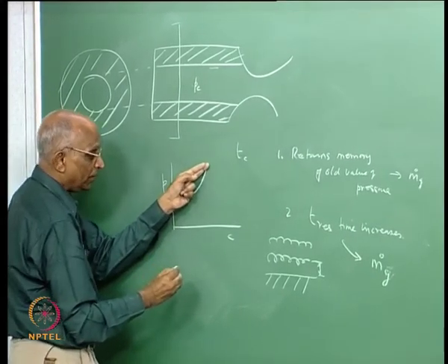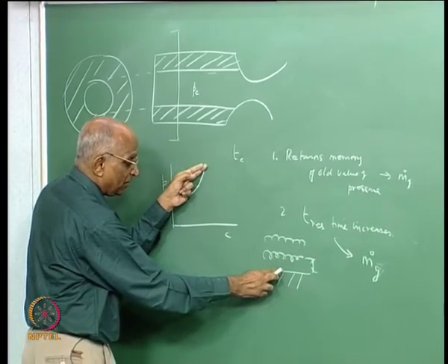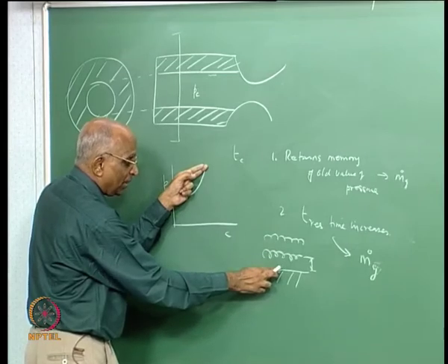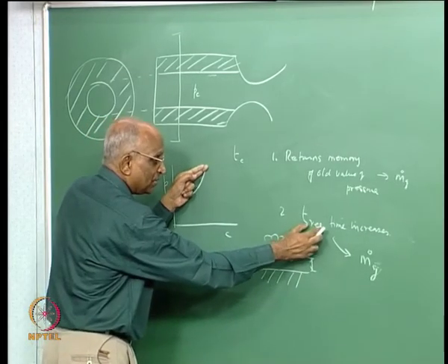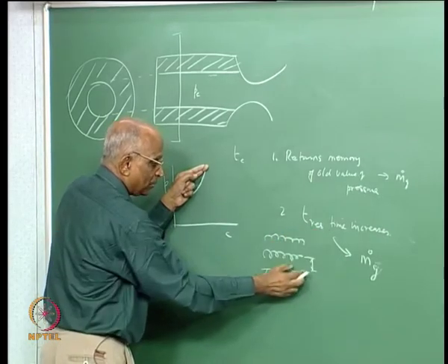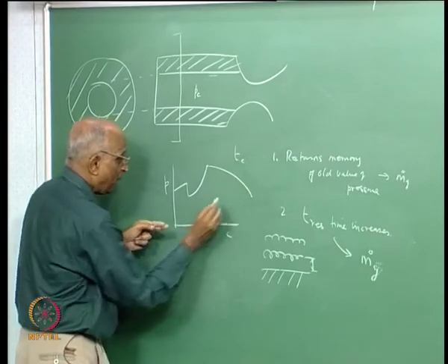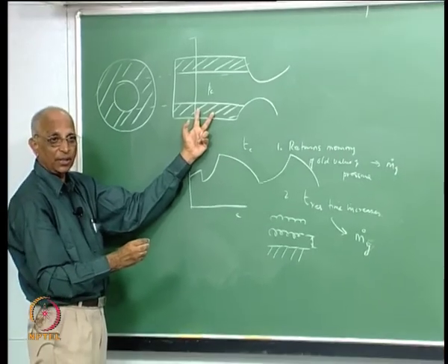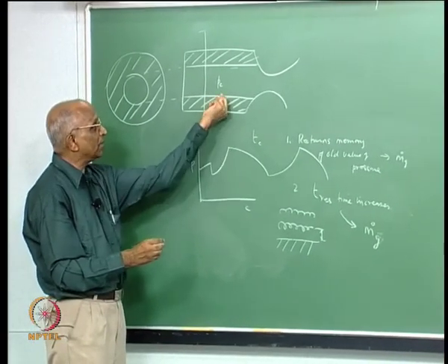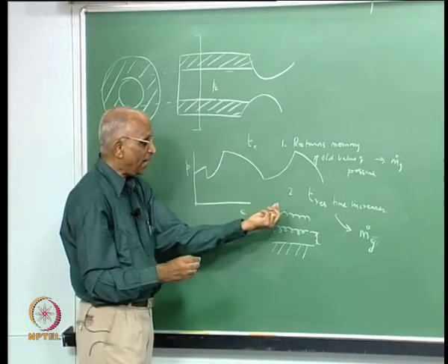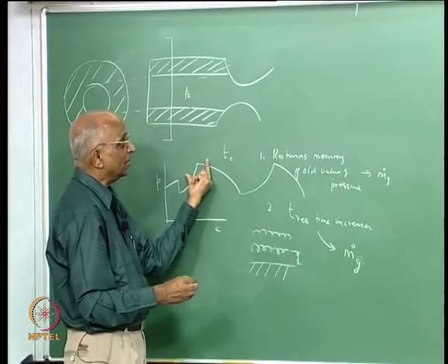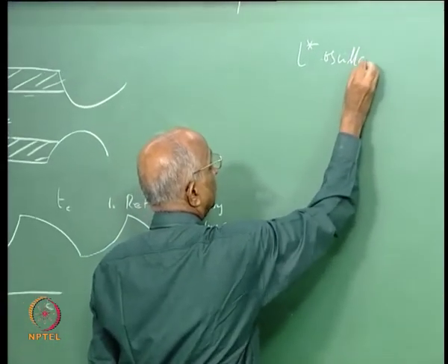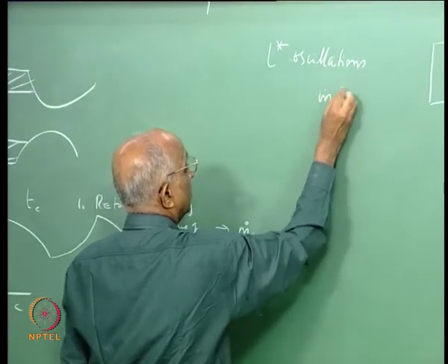At higher value of pressure, the memory of the surface is with respect to the older value of pressure, for which the mass generation rate is lower, the residence time is less. If residence time is less, I have smaller chemical reaction time to generate gases, and therefore it again falls back. Again I have this, and the same thing is possible even in a solid propellant rocket, namely whenever there is a delay due to the thermal lag at the surface and the residence time gets changed, I can get this oscillation, and this is known as L star oscillations in solid propellant rocket.